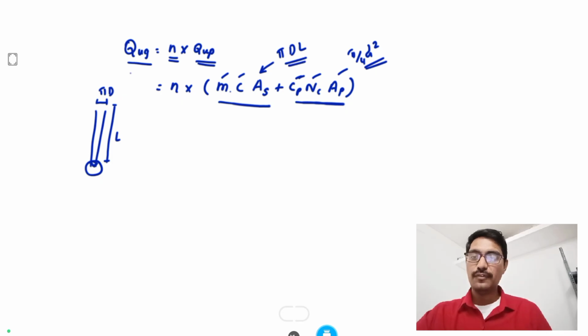Okay, so the static formula is mainly based on static piles, that is the non-displacement piles, the cast in situ piles. If we go for the dynamic formula, we can use the Engineering News formula and Hiley's formula. Those formulas are for driven piles.